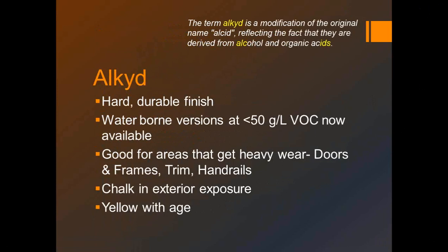And even with the new waterborne alkyds, you still have that hardness of finish, and they are resistant to hand oils and the chipping effects that you get from bracelets and rings and dinging the surface and so on. So that would be a good place. Again, those doors and frames, a DTM acrylic or an alkyd product would be fine in that circumstance. Interior stairs, metal stairs, handrails, things of that nature. We use them sometimes on walls, we use them sometimes on masonry surfaces, depending upon what we want to achieve.